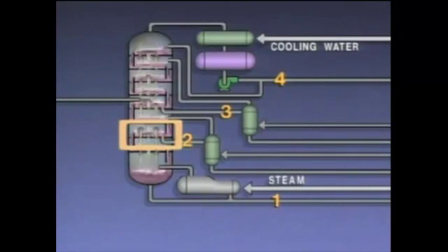While there may be some overlap of products in this area, the concentration of product 2 is highest in the liquid that is drawn off at this point. If conditions in the tower are controlled properly, the concentration of each product is highest at its respective draw-off point. Let's take a moment to see how draw-off is collected.